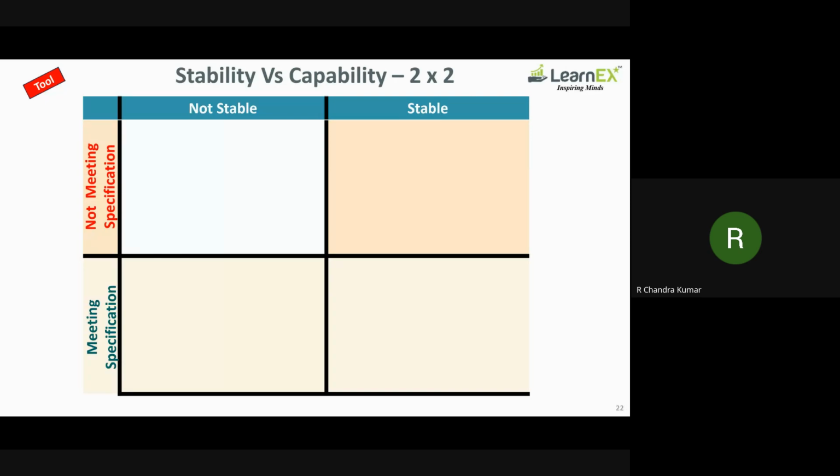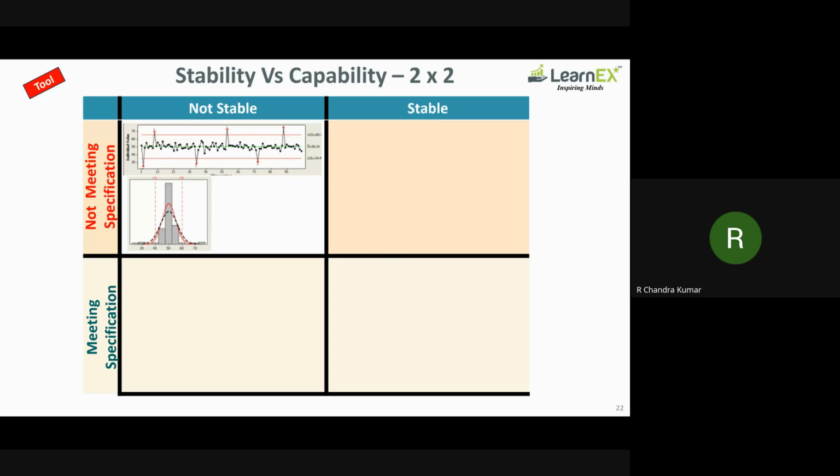So one thing to understand from the data is whether the data is consistent or inconsistent. That means whether outliers are there or not. This is a basic thing that we can know by using control charts. Control charts will have control limits. If points go beyond the control limit, it means it's a special cause or outlier or abnormality. It doesn't depend on the specification limit, irrespective of whatever the specification limit is. Suddenly one day it is different, an outlier. So what was the change event that day? That needs to be analyzed separately.